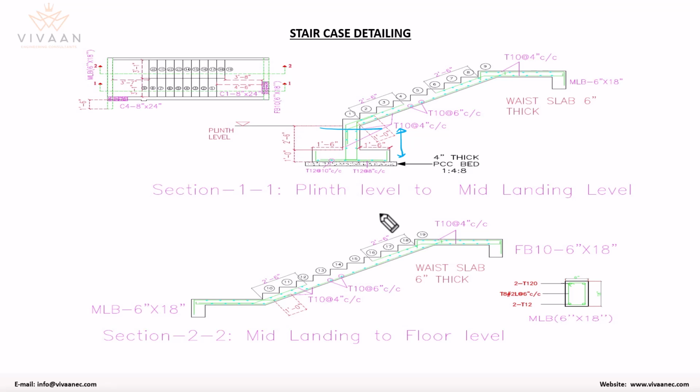Okay, although we may not require to go like 6 feet, at least we may require to go for like 1.5 feet or 2 feet so that we'll be getting a proper strength and proper tightening will happen, and we are going to get the grip when the loads transfer as well. Because even in the ground floor, we need to transfer part of this staircase load to the footing of the staircase, right? So this as well should be properly done.